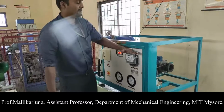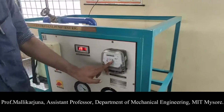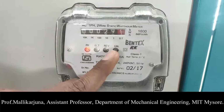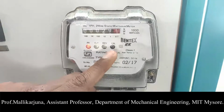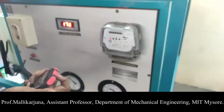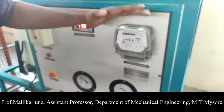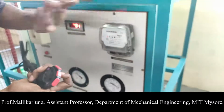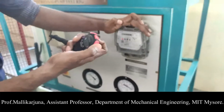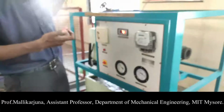Okay, now to measure the energy supplied by the motor to the pump, we need to look onto this device. One of the LEDs is blinking over here. For a fixed amount of time, how many times this blink is going to happen, that needs to be recorded. Let us go through the stopwatch now. So I have started the stopwatch. For a minute, how many blinks we are going to take, or else for a fixed number of blinks, what is the amount of time taken. In both ways, you can measure the energy supplied by the motor. So now this reading has been taken. So now we are aware of the energy supplied by the motor to the pump.